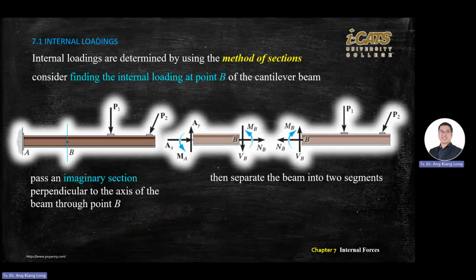So you solve for the left-hand side first. Cutting forces always point out. For shear forces, there is a rule that I will detail later. You can draw it up also, but usually if there is a shear force on the left, I just balance it by inverting the vertical force to the other side. So in this case, it points down. You might ask, hey, Dr. Ang, can I point it up? You can, but later in your calculation, you will find it points down.